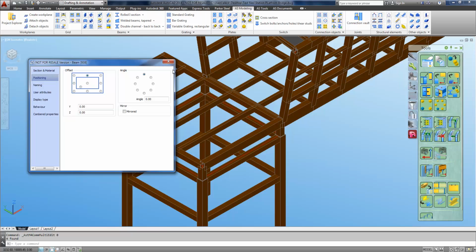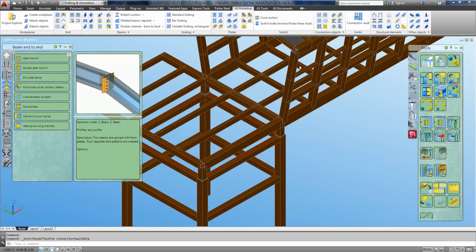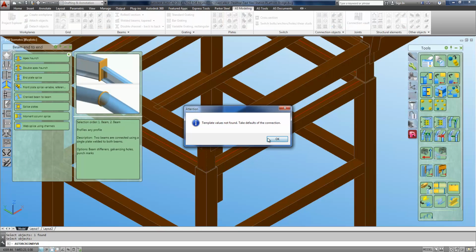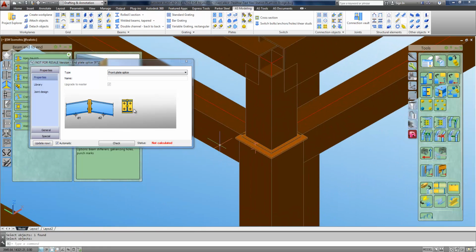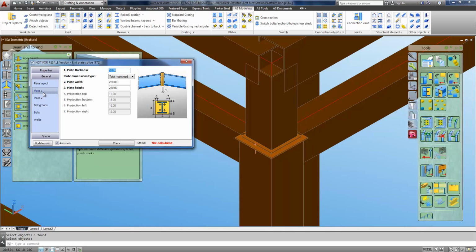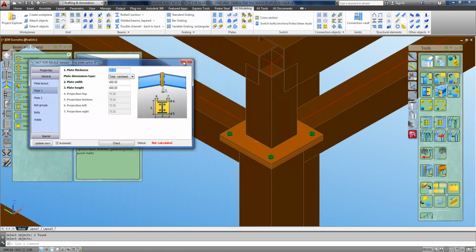It understands and knows how to manipulate and utilize different members and also orientations and so on. Top of steel, center of steel. It's got built-in commands for connections, and for example here we'll just add a connection between these two components. It understands how to shorten the steel to accommodate for any weld preps. In this particular case, the weld has been added to that, and it really just starts to add the detail